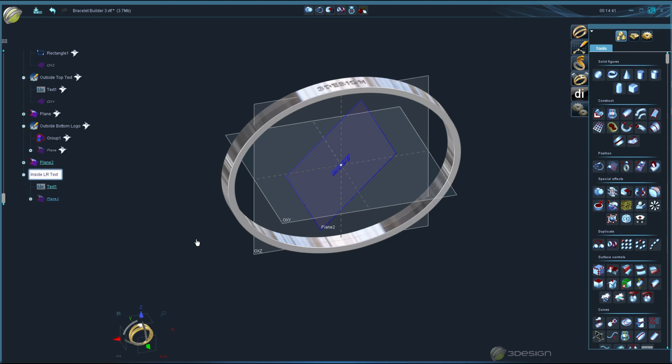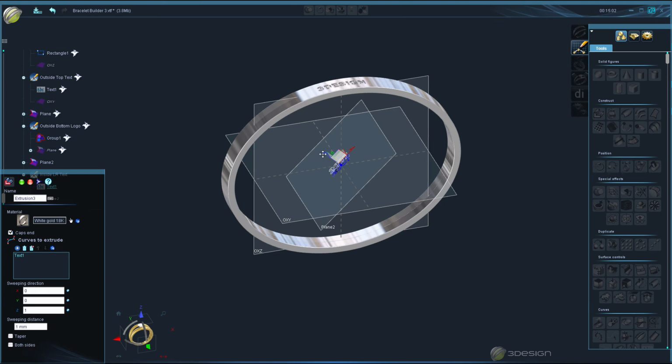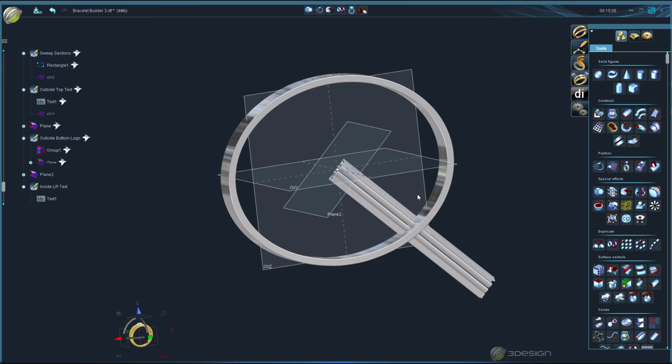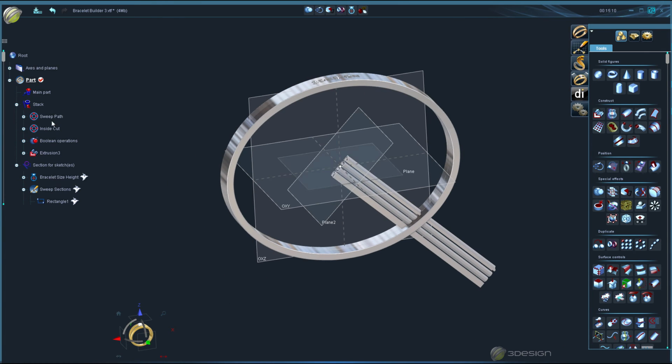And you can use maybe 4 o'clock for the clock position. You can use degrees. Whatever label you want to remember, that's going to be the lower corner. And that works for me. I'm going to select that font or text and extrude it through. Make sure we grab just the Z arrow, push it all the way through, and validate. And we're ready to cut that.